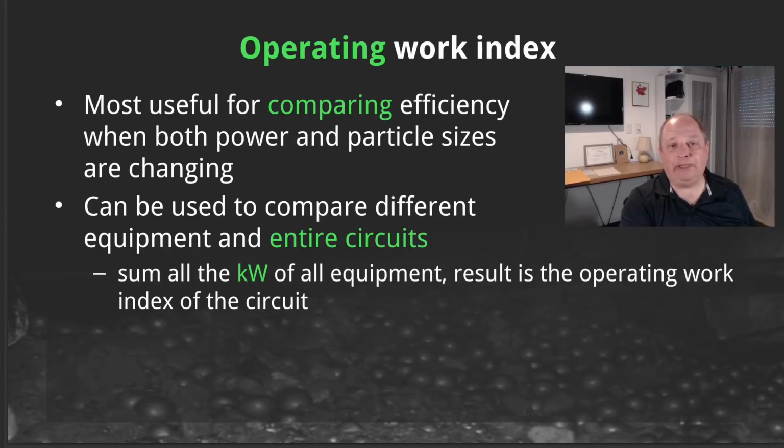Commonly it's used to compare the efficiency of a circuit when you see things like the power draw changing and particle sizes changing simultaneously. You can't really use specific energy consumption to measure grinding efficiency if the feed size is changing or if the product size is changing.